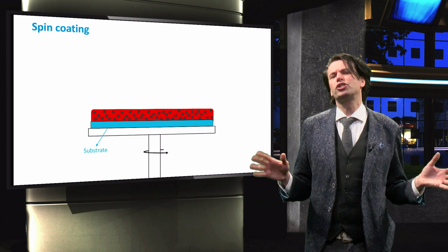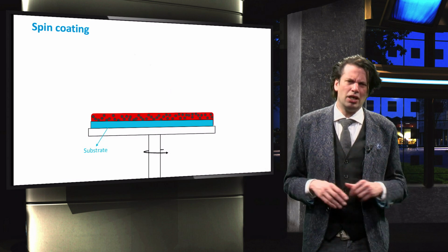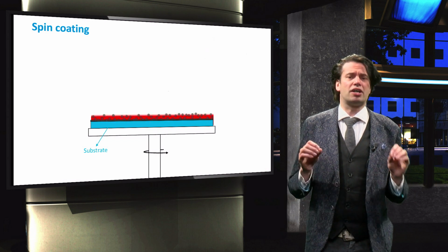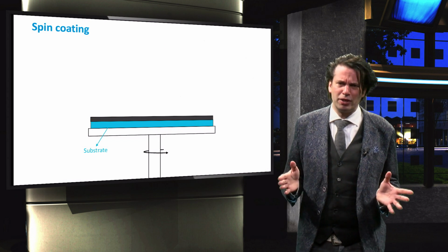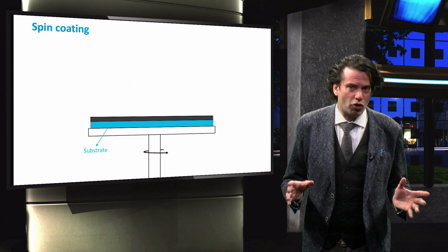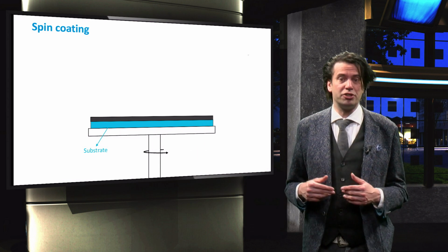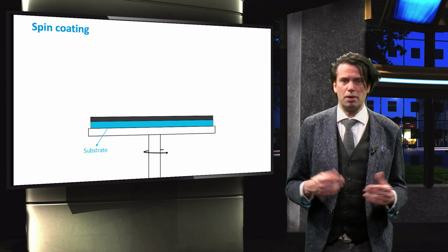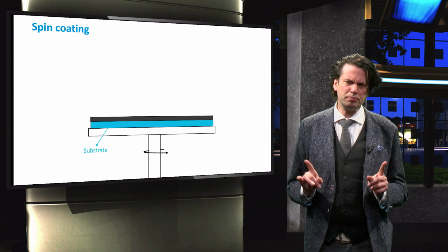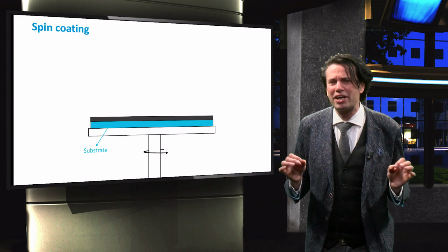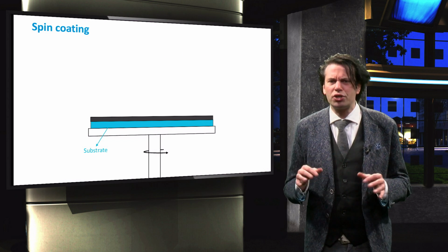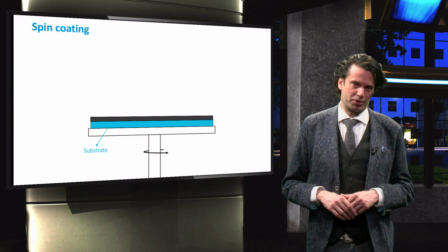Since the target material is usually dissolved in a volatile material, the solvent evaporates during the spin sequence. Eventually, only the target material is left, leaving a thin film with a homogeneous thickness. Besides the volatility of the solvent, the evaporation rate of the material also depends on the flow rate, temperature, and humidity of air passing over the substrate. The process becomes more complicated when depositing nanolayers for organic electronics, where a highly ordered nanoscale structure is very important.